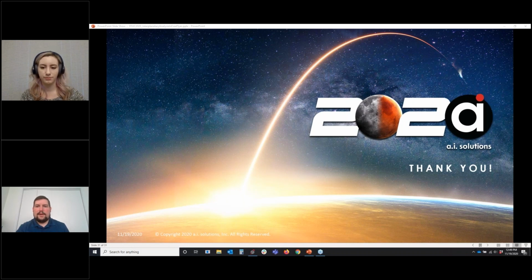Gotcha. I think the last question that I have so far is, could you export a celestial object that you have set up? Yeah, so you can export your custom celestial objects as FreeFlyer object files if you want to share them among multiple mission plans. You can also generate SPICE ephemerides using your celestial objects or your spacecraft through FreeFlyer. So there are a lot of different ways that you can export those and share them among mission plans.